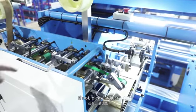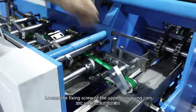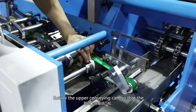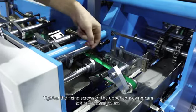If not, please adjust. Pull the lever of the conveying can to raise the conveying can. Loosen the fixing screw of the upper conveying can. Rotate the upper conveying can so that it will not press the rope. Tighten the fixing screws of the upper conveying can.